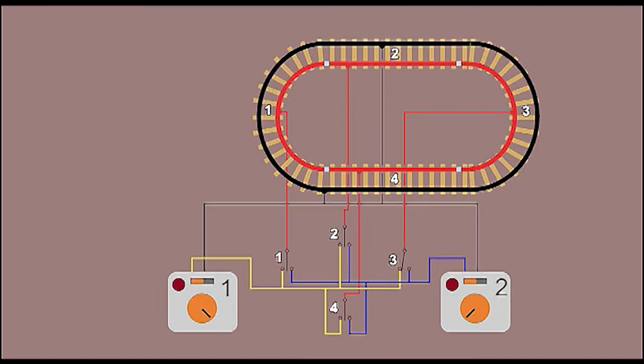If the trip doesn't blow, with all the rolling stock off, then the problem is somewhere in the rolling stock. So put them on one at a time back on the track and see which particular item is causing you the problem.